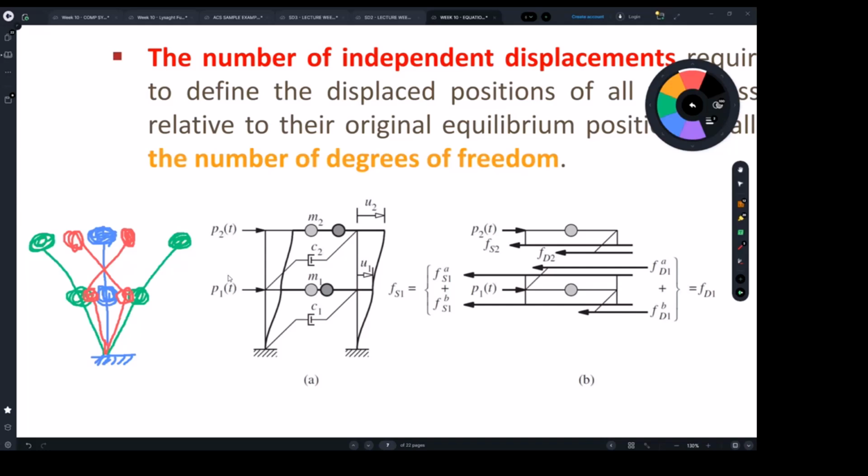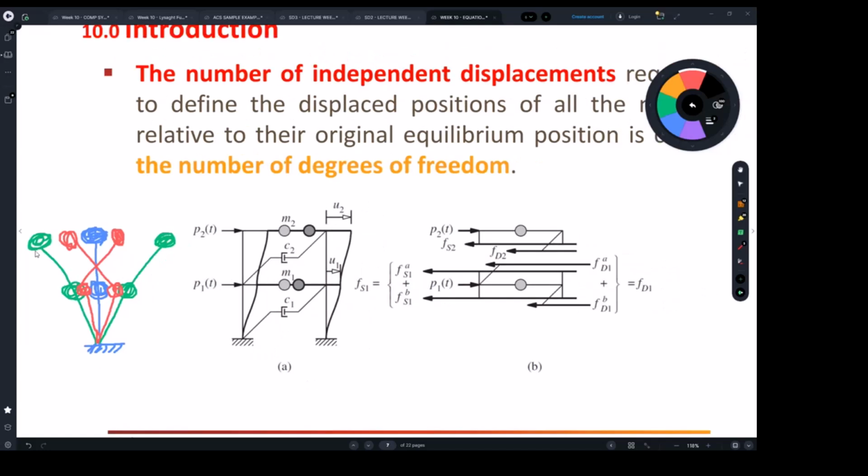because the key thing we always, as dynamic engineers, when we talk about vibrations and frequencies, one of the key parameters we inspect and evaluate and design with is the frequencies, time periods, as well as the mode shapes, which give us displacement. So the green mode shape will typically be calculated with higher time period than the second mode shape. And whenever you go more and more with the degrees of freedom, like third mode, 7 mode, 8 mode, if you have more and more floors, the time period will get reduced and the frequency is high.